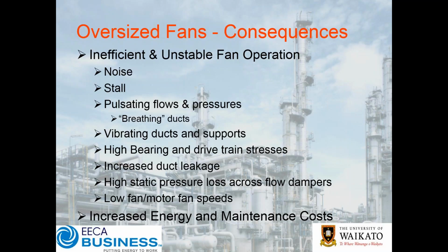It's quite common to hear people talking about ducts that breathe and oscillate. We can start to get vibration in our ducts and supports. We can have higher bearing loads and drivetrain stresses, and increased duct leakage.